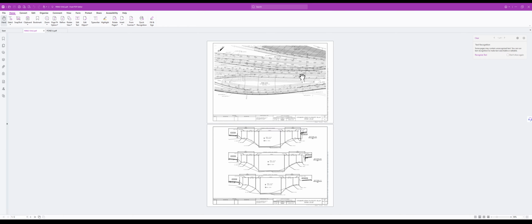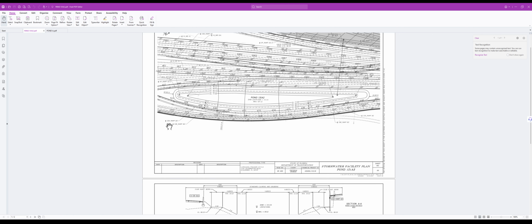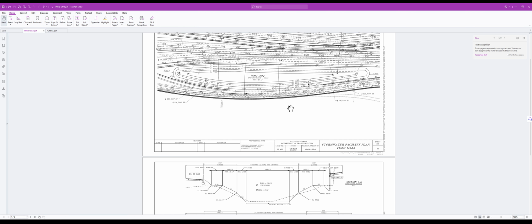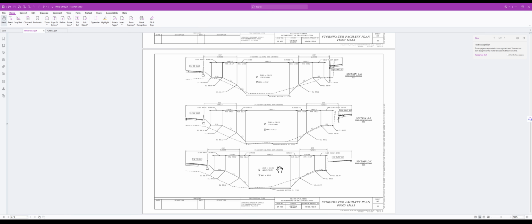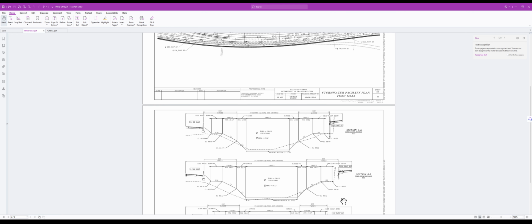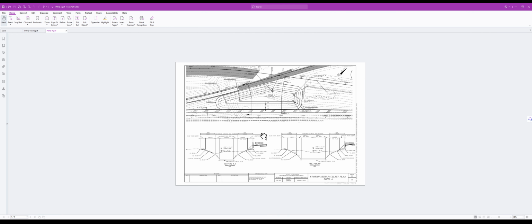So it's always important, if somebody assigns you to do something, to ask them, please give me a PDF that's already done and approved. Why? Because EORs have preferences. And I kid you not, some people will just tell you, I don't want this tick, this line, this label, and so on. So always talk to them and ask them, please show me what you have so you can mimic it and do it, right? Because at the end of the day, making these plans is all a preference of the person who's going to sign and seal them. So if they like them a certain way, you need to make them in a certain way. Period. Okay, so these are examples.